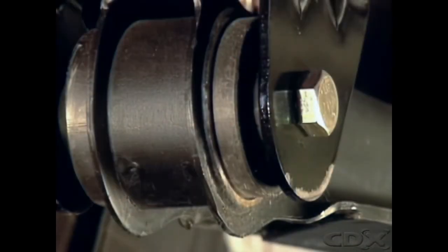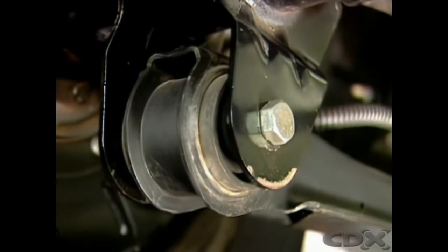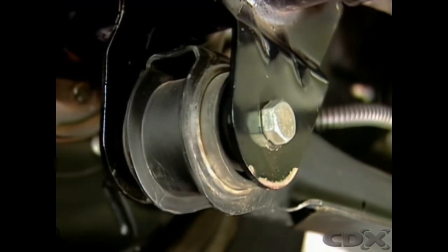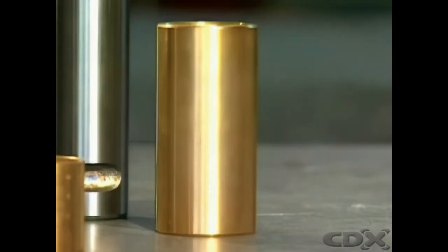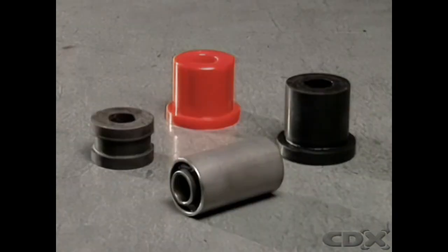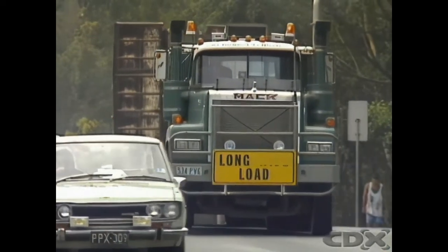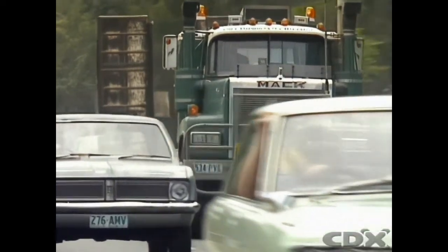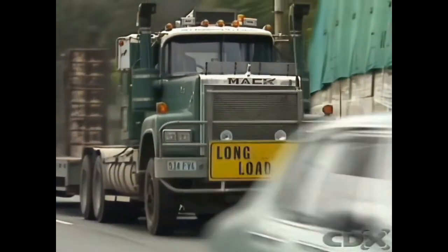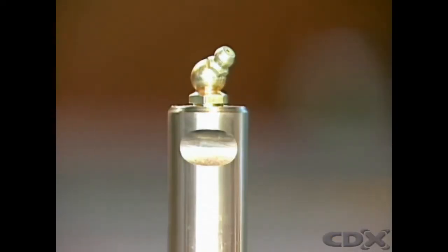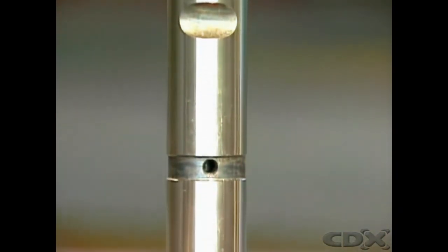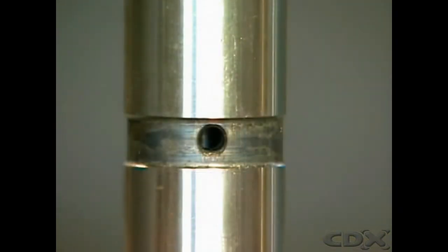Bushings act as bearings at suspension fulcrum points to allow for movement of the component while maintaining its alignment. They can be metallic or made of rubber, nylon, or urethane. In commercial vehicles, metallic bushings are commonly used as shackle bushings for leaf springs. Any force applied to the bushing acts through it to the body of the vehicle, which results in a harsher ride. The mounting pin on a metallic bushing is usually drilled to allow for lubrication.